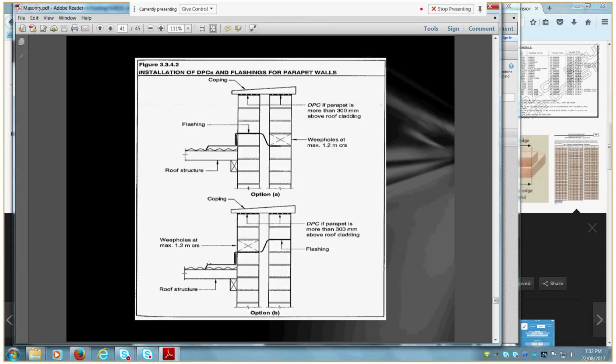Typically, yeah, there might be some parapet walls on these designs. Like a chimney thing as well. No, I suppose it's a bit higher than basically where your gutter line is. Have you seen many newer houses these days where you just see basically the wall continues straight up? Yeah. Basically, the roof comes in behind it, and that's where your box gutter is, and it exits the water that way. That part where it is a bit higher is called a parapet.